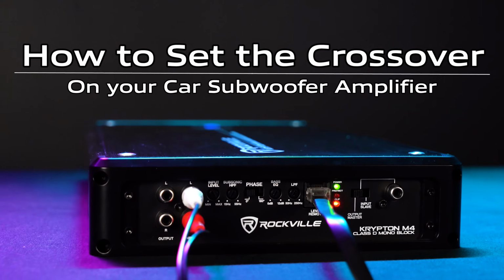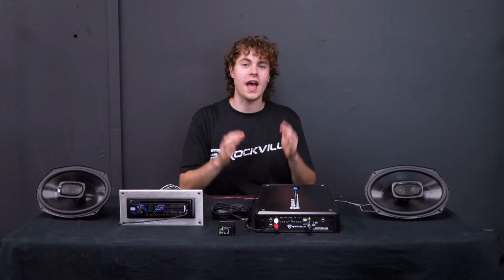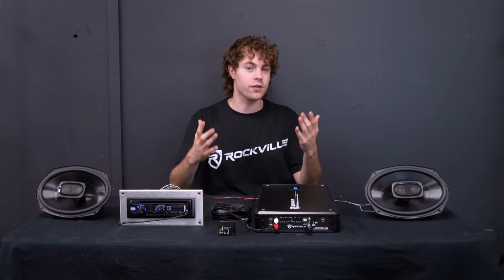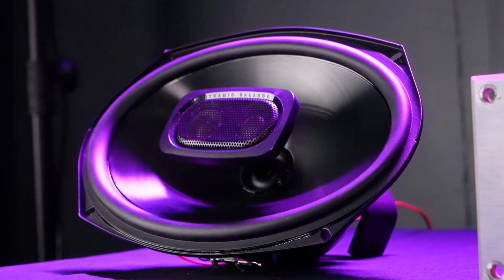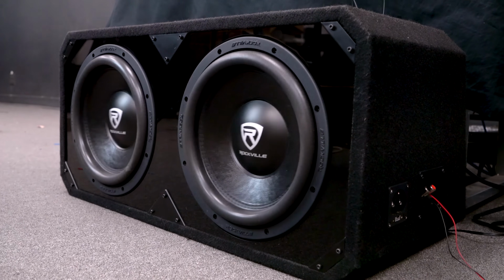Today I'm going to show you how to set the crossover on your car subwoofer amplifier. The main purpose of setting the crossover on your subwoofer amp is to have nothing but bass and low end playing through your subwoofer. By filtering out the high end of your subwoofer, the full range speakers have the room to play the mid and high range frequencies, while your subwoofer handles all the low end.